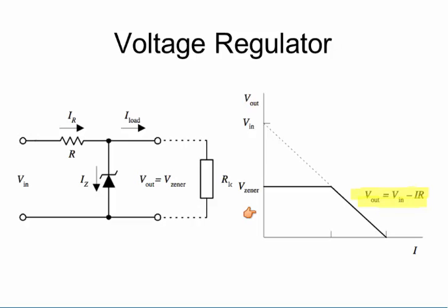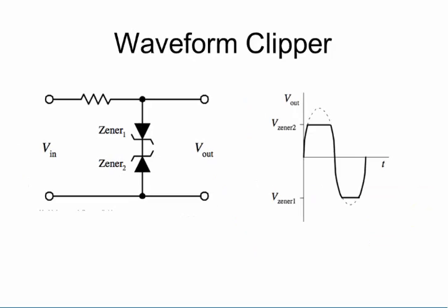So it's a very good regulator for the majority of the operational mode. If you use it carefully and it operates over here, then it's a very good voltage regulator. If the current becomes too large, the voltage will start falling backward, will start decreasing.